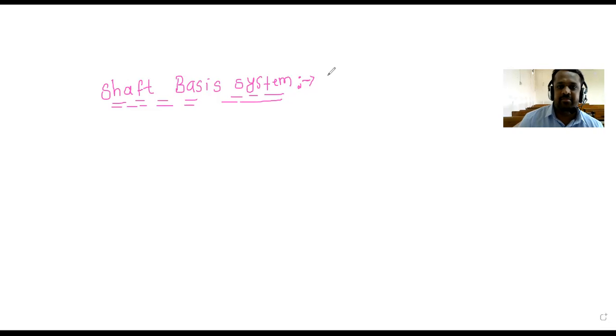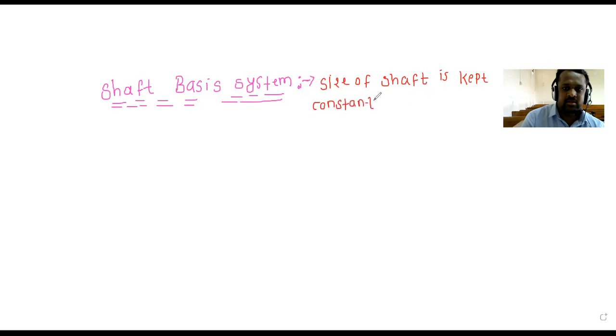In this shaft basis system, the size of shaft is kept constant, and the hole size is varied to get the different fits. It is called the shaft basis system.